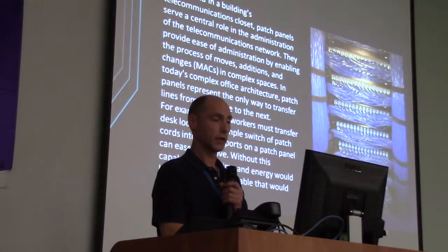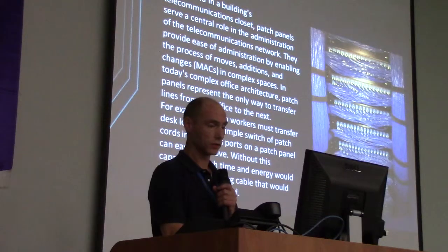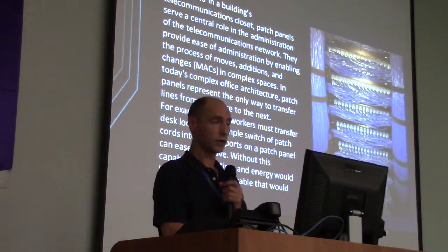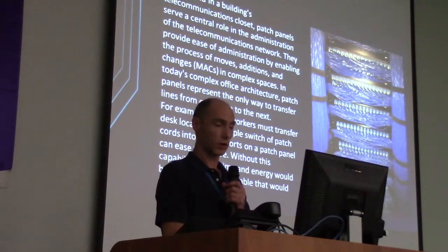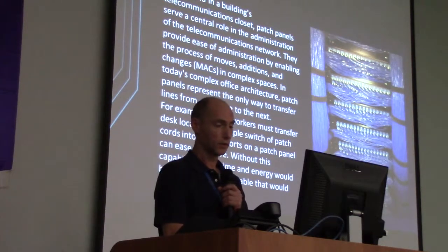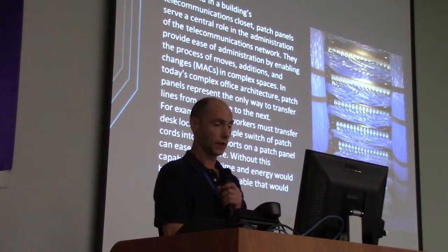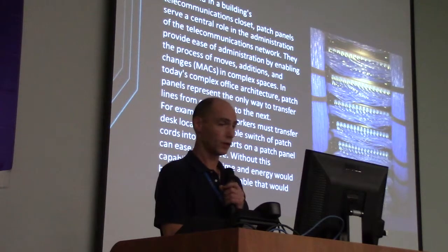Often found in a building's telecommunication closet, patch panels serve a central role in the administration of the telecommunications network. They provide ease of administration by enabling the process of moves, additions, and changes in complex spaces. In today's complex office architecture, patch panels represent the only way to transfer lines from one office to the next. For example, if two workers must transfer desk locations, the simple switch of patch cords into various ports on a patch panel can ease the move. Without this capability, much time and energy would be spent terminating cable that would have to be hardwired.